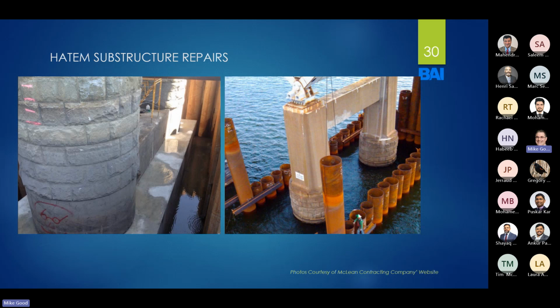And so what they did was they put these piles all the way around, created a cofferdam, dewatered it, mucked it out, did the substructural repairs that needed to be done, and they left them in place. So this was a really unique and a really neat kind of project to have been involved with. But again, it illustrates the effects that scour can have if it's not addressed.